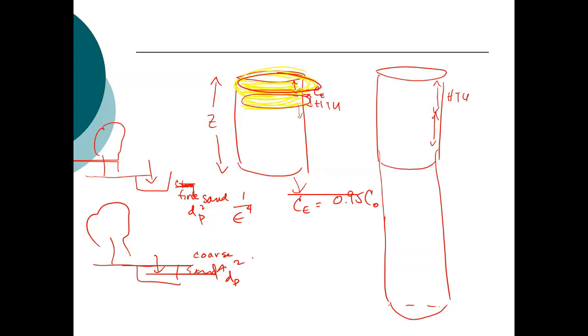Yeah, so for the granular, is there an optimum grain size we're looking for? Typically, it's about the grain size of a medium grain sand. Kind of think of it that way. The larger you get, the longer it takes typically to reach equilibrium, because there is less surface area.